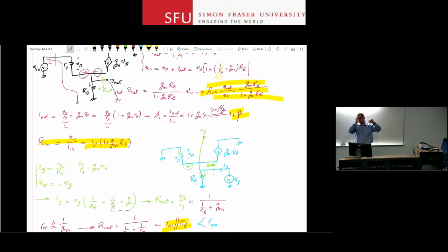In this case, sometimes you may want to put a buffer in between the source and your main amplifier. And then what you do is that you take the voltage from the source, you show the source a very large input impedance, monitor that voltage, take it out, and then you put a second amplifier stage after it that can now work with the source, in this case with low output resistance, right?